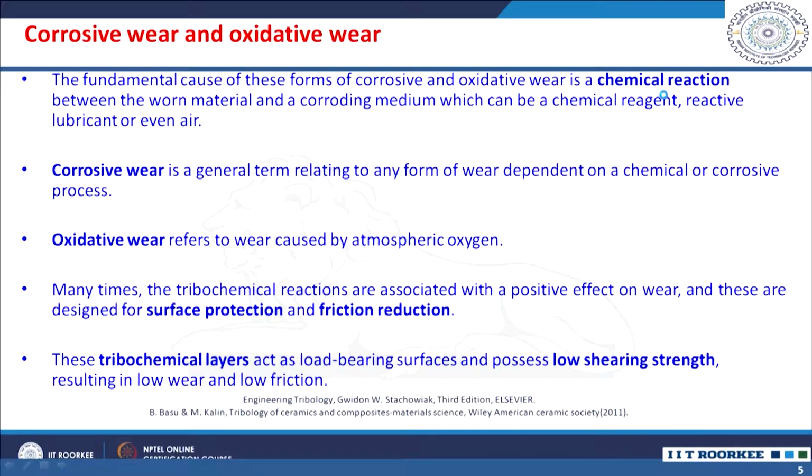The fundamental cause of these forms of corrosive and oxidative wear is a chemical reaction between the worn material and a corroding medium, which can be a chemical reagent, reactive lubricant, or even air. So, you can also say corrosive wear and oxidative wear are synonyms for tribochemical wear, only their kinetics are different. We will also try to understand corrosive wear and oxidative wear in this class.